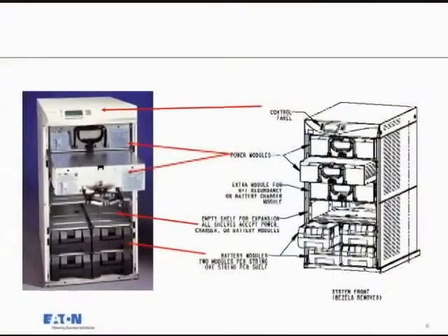So we've taken that technology previously, and again, this is that 3 kVA single-phase application. So we're not talking simply large systems, we're talking small single-phase systems as well, where I have 3 kVA modules, then I can go 3, 6, 9. So I can start at 3 kVA and expand up to 18 kVA in 3 kVA increments. I can add redundancy if need be. I can scale forward, I can scale backward. If I look beneath the cover here, the initial designs look something like this.